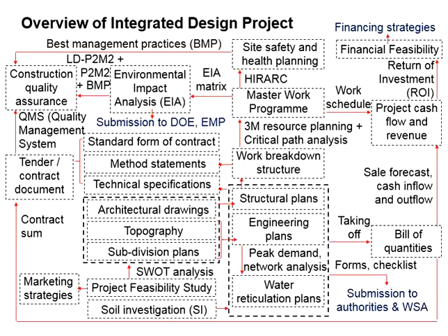Now, the type of the foundations to be used is dependent on the soil conditions, whether the soil has sufficient bearing capacity in undertaking the weight of the structures. That's why we need the soil investigation reports to know the conditions of the soil.